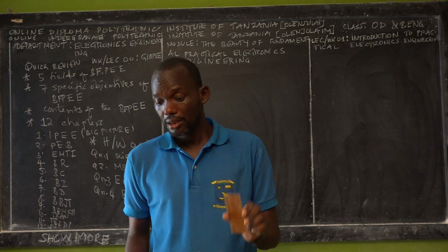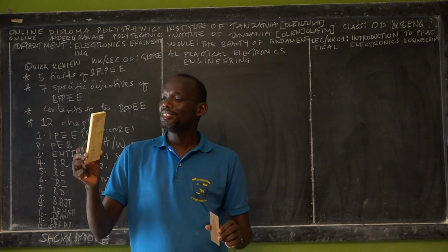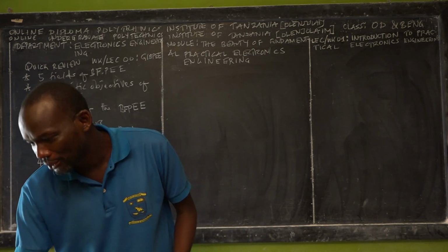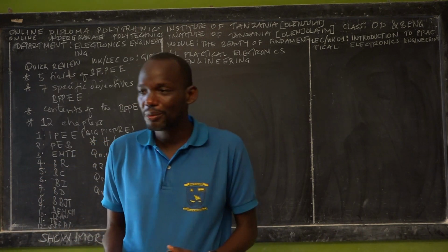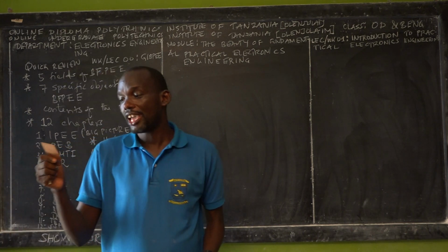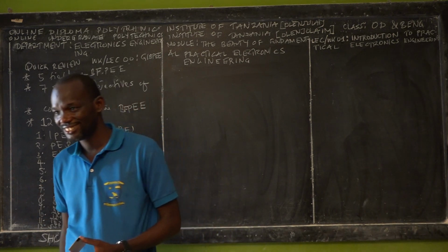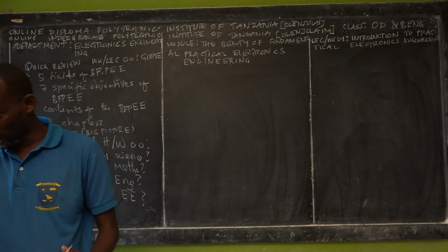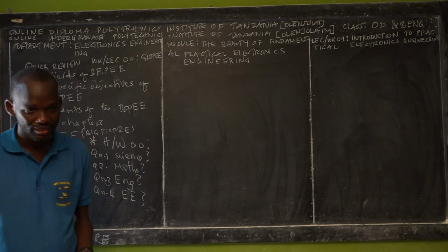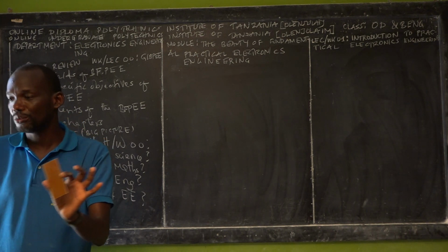Are we together? Yes. But now, why is this fundamental? Because you are allowed, it means they will give you permission to test your circuit even 100 times without buying another breadboard. But once you build on this veroboard, and then you made a mistake, or maybe you want to do modifications, you have to find another veroboard and start to desolder the components from this one, and then you solder on another new veroboard, similarly to this one.